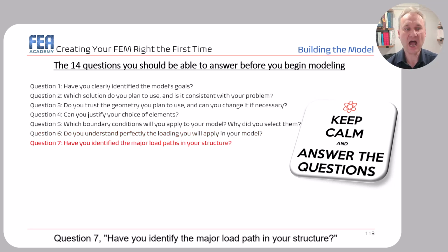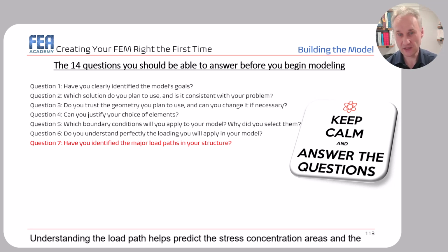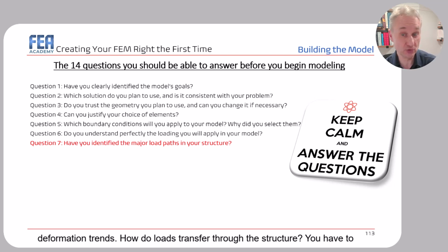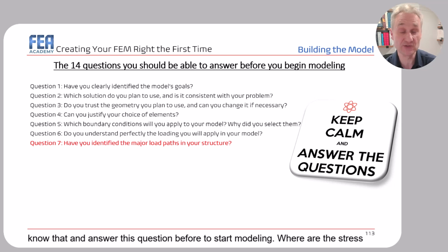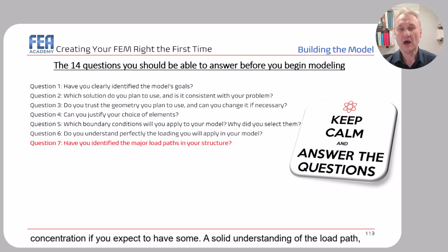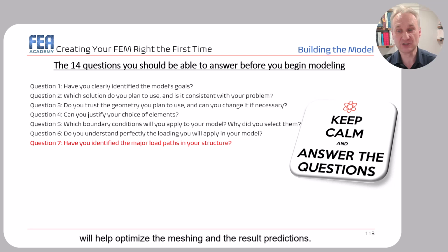Question 7. Have you identified the major load path in your structure? Understanding the load path helps predict the stress concentration areas and the deformation trends. Okay? How do loads transfer through the structure? You have to know that and answer this question before starting the modeling. Where are the stress concentrations, if you expect to have some? Okay? A solid understanding of the load path will help optimize the meshing and the result predictions.